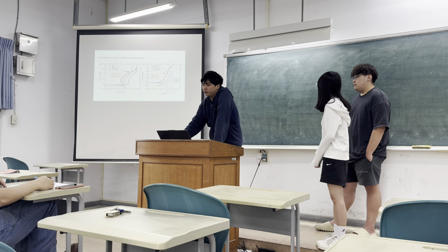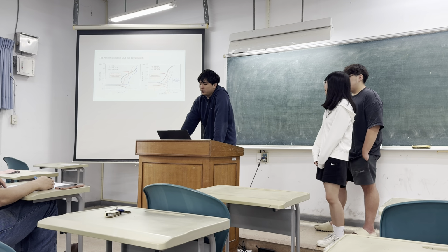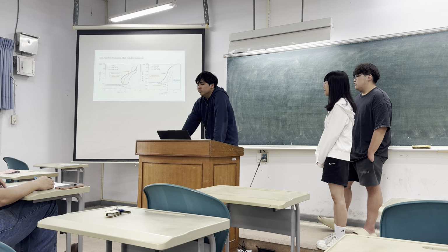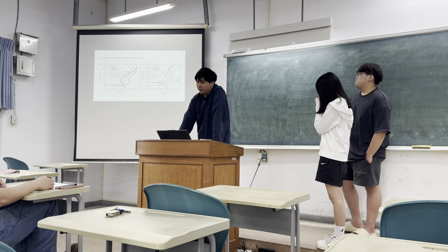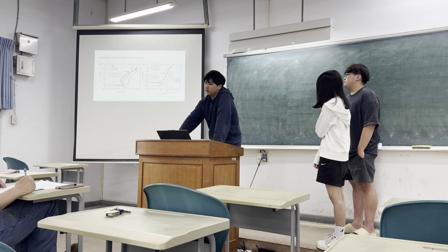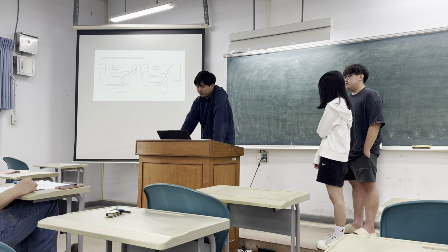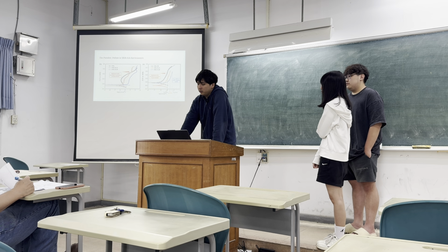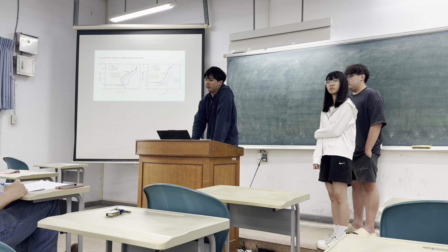More critically, by tracking the pitting potential, we can see it shifts to more negative values in the presence of SRB. This tells us that the passive film has become unstable. It can no longer protect the steel at higher potential, and the material becomes prone to localized pitting much earlier than expected.